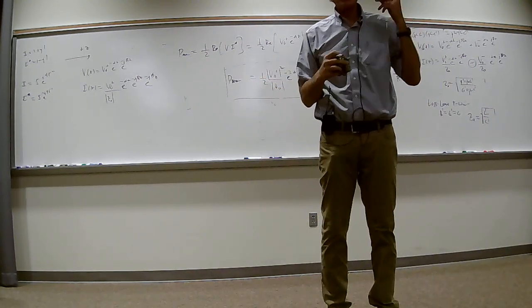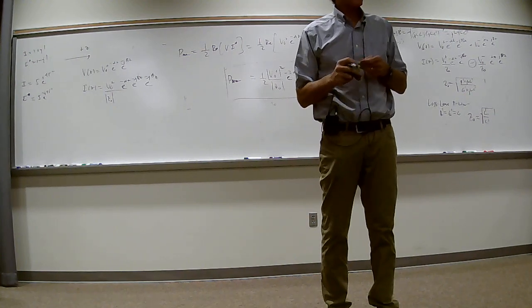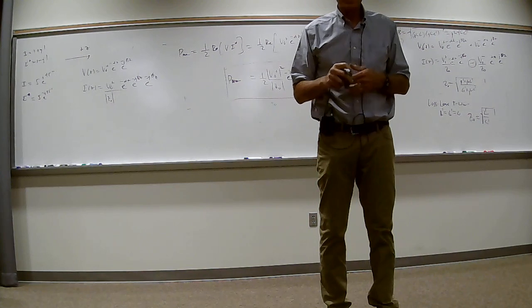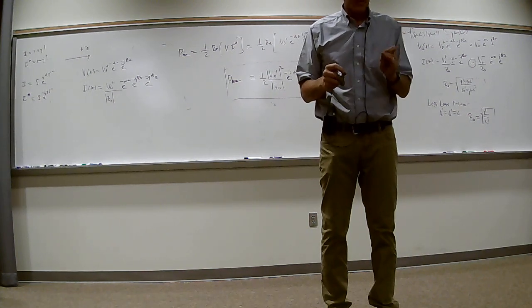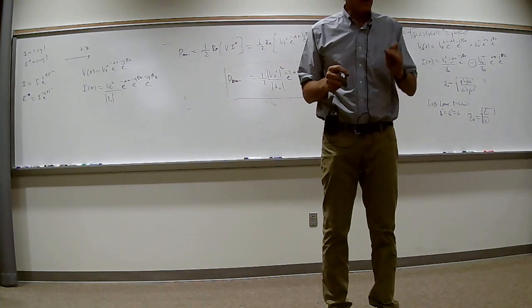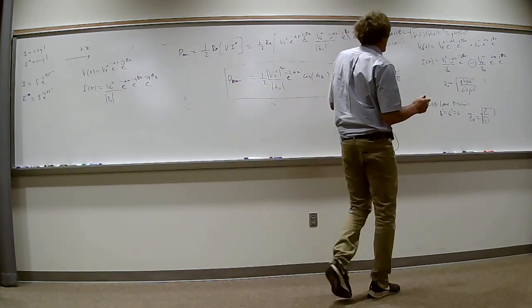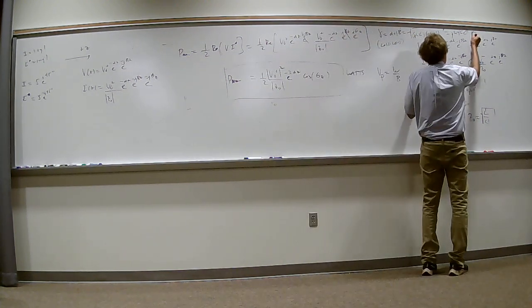You'll notice it's just j times omega square root of LC plus 0. Alpha is necessarily 0 if it is lossless. Are you with me on this one, class? How many see this right here? It must be. That just tells you it's lossless. All right, this is beta.